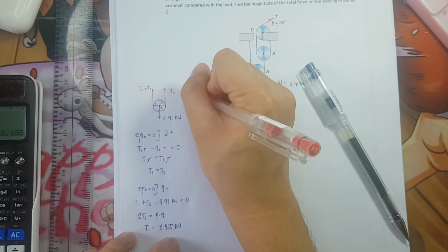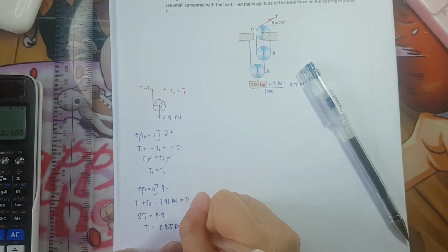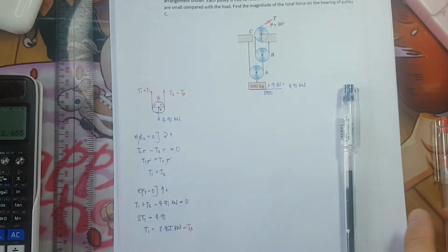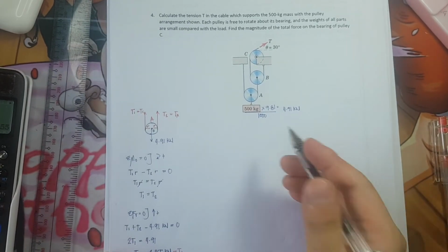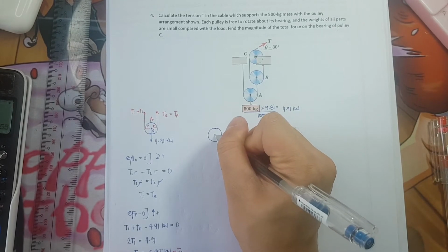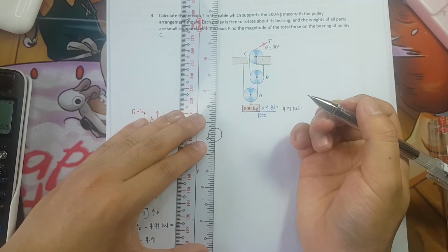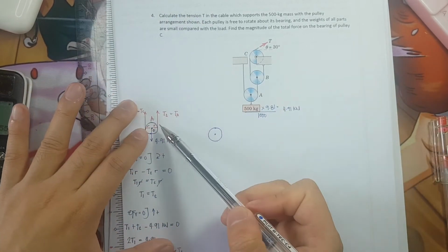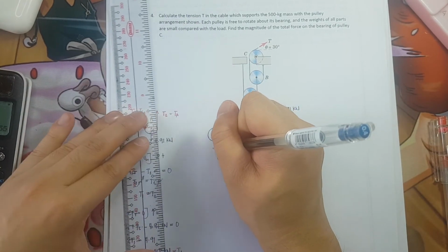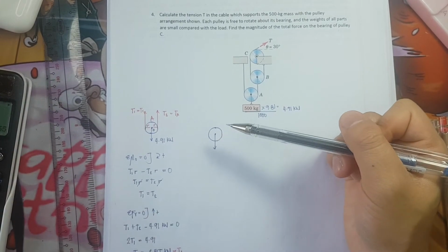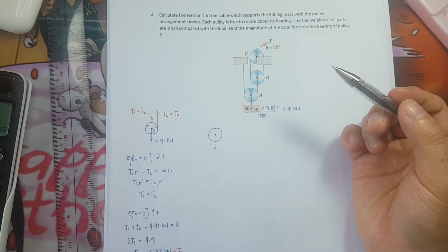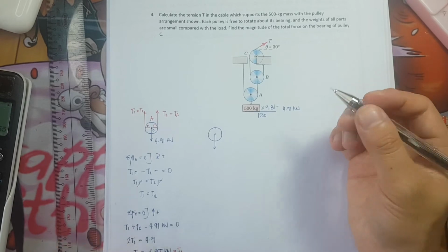Okay, and this T1 is equivalent to TC, and this is equivalent to TA. Therefore, T1 is also equivalent to TA. So this is roller A. Now, redrawing roller B, I'll be redrawing here my pulley B. Since here the tension is pointing upwards, I am going to redraw it here in a downward manner, just to cancel out the force, like what we have discussed in the previous discussion.